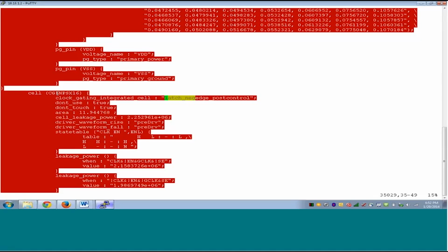If you go to 2 or 3, then a lot of clock gates will be inserted with less saving in power. So you have to choose a value which is either 4 or 8 or something like that, not too low and not too high. What that would mean is that if you choose the value to be 8, each of your clock gates would be driving at least 8 fan-out. So it is very important to have multiple and higher drives of clock gating cells. The lower drives are of no use. Whenever you have multiple drives available, choose the one that matches your minimum bit width. For example, if X8 is available, I would recommend choosing either X4 or beyond, not below X4. So this was about the library.